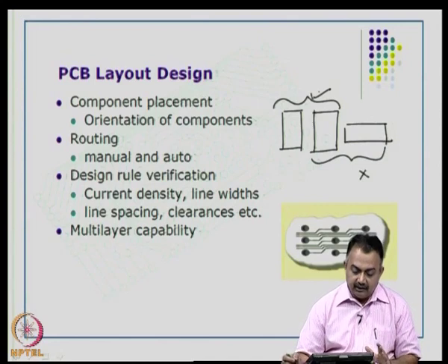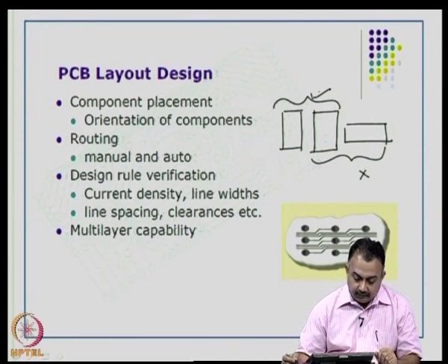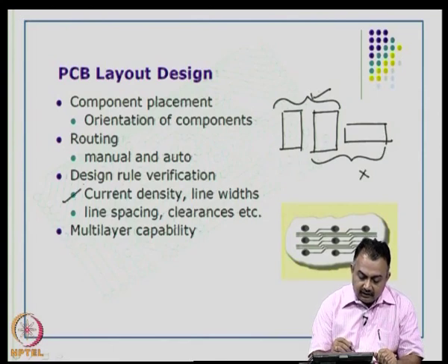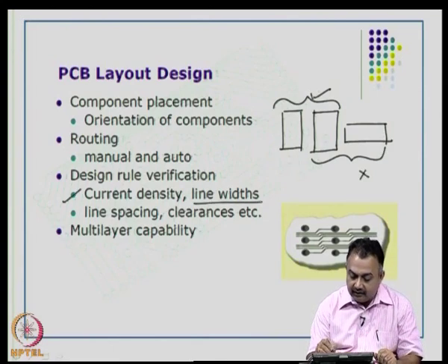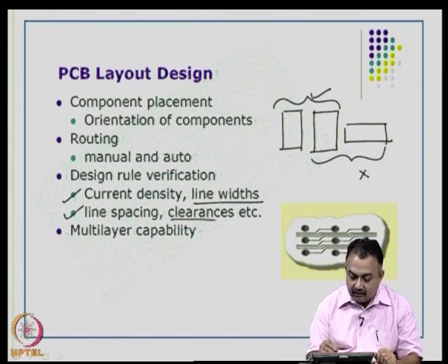various aspects in placement, then comes routing, that is manual and auto routing of the interconnects that you have specified in the schematic capture. Then you can do a design rule check or a design rule verification, basically to look at current density, the line widths that you require for manufacturing, line spacing that is specified by the manufacturer, clearances